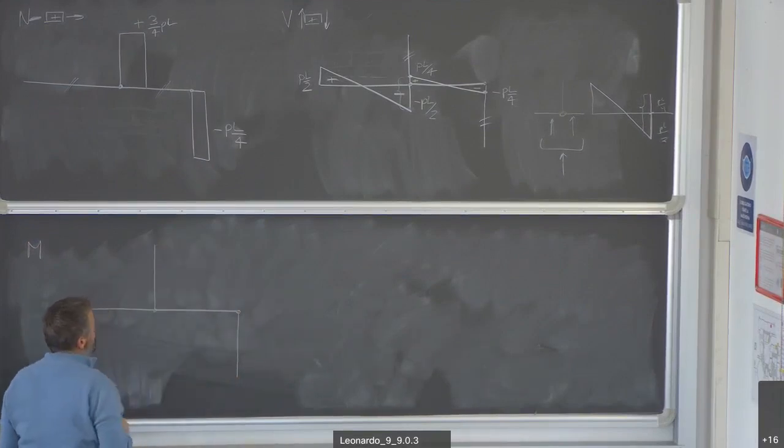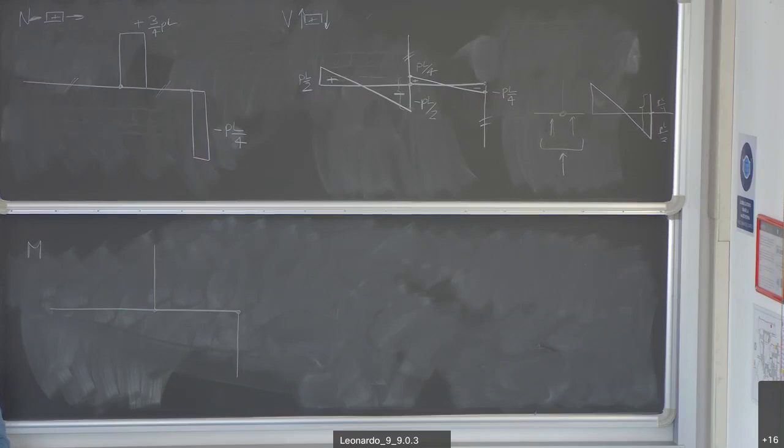Basically, yes, but from the mathematical point of view, I know that when there is a beam subjected to distributed load, moment should be continuous and parabolic. Moreover, both on this beam and on this beam, I know it's starting from 0 and it's ending at 0, okay? What do you mean continuous, Professor?